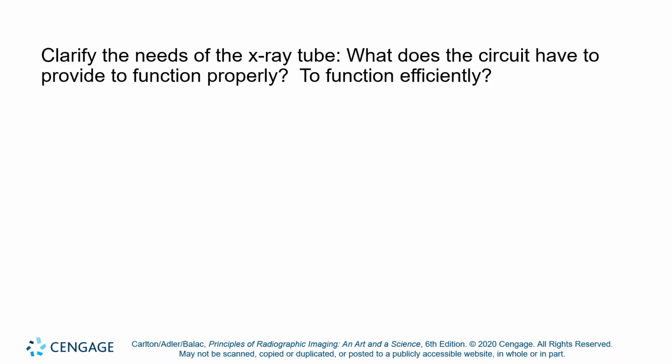We want X-rays that we know their average energy. So we have to have a dialed up voltage. We need to know how many X-ray photons we're sending in the beam. So we need to have a way to set the tube current. Yeah, those type things.